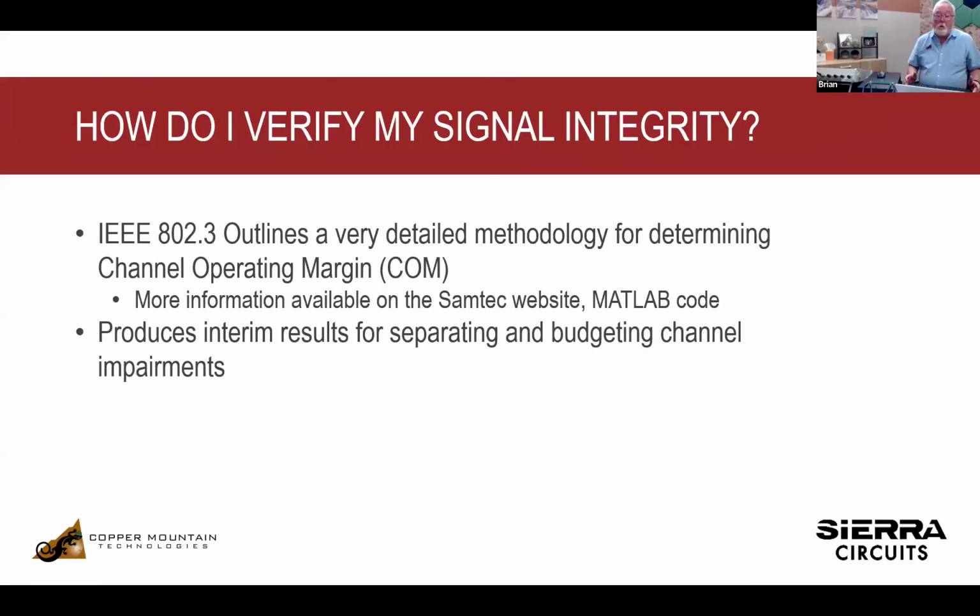There's something called effective return loss. So it may have an actual return loss of 9 dB, but an effective return loss of 20 dB after error correction. And COM, I think, comes up with an answer for that. So that's something you might want to look into if you want to put a number to how good your board design is for digital.